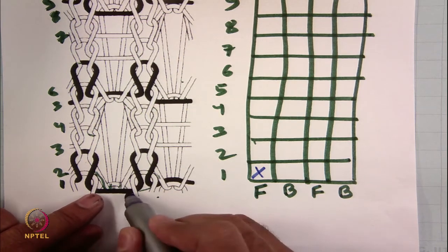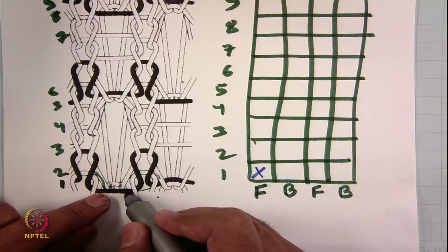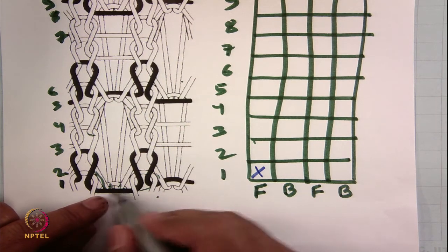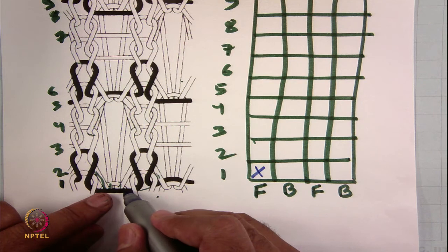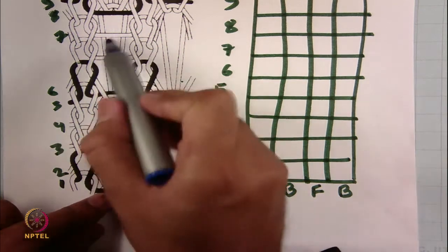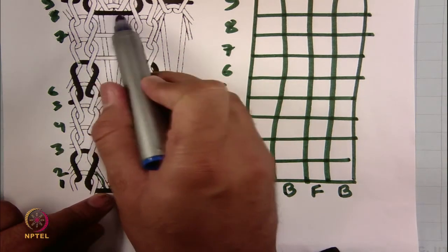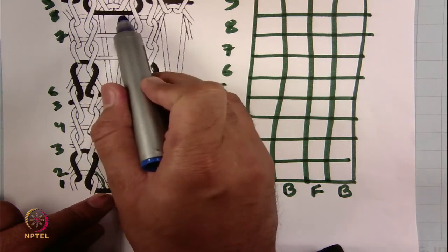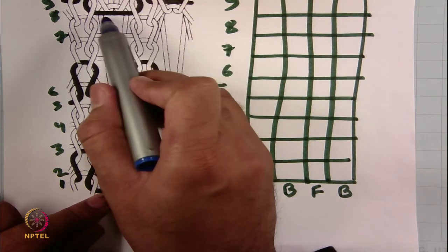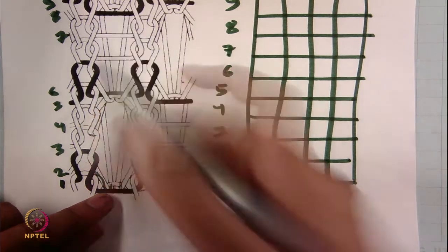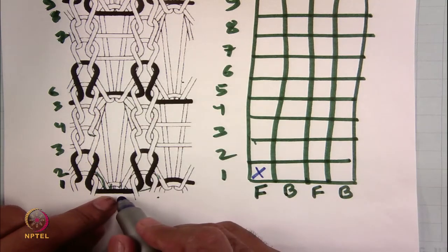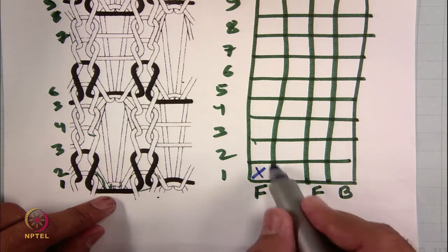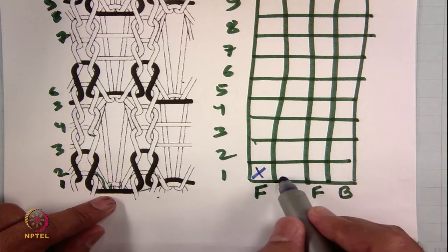So, this is in a straight condition and it is not engaging with the old loop, because if you carefully see, naturally this particular loop is a float stitch because it is in a straight part and it is visible towards the leg side. It is not towards the head. So, the needle is not catching this yarn. When the needle is not catching this yarn, naturally it will be in a float condition. So, in that case we will keep this box blank.